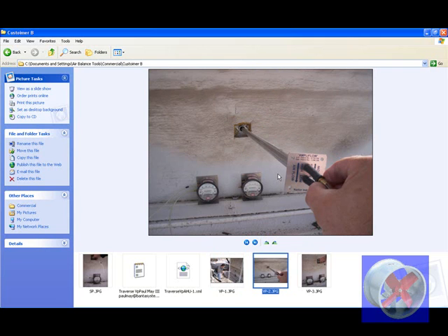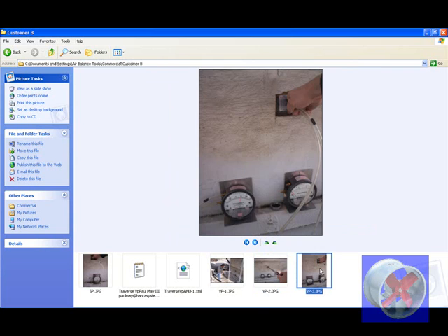So air is coming across this way. There's holes along this tube on both ends. These tubes lead into the magnehelic. We have the magnehelic high side and the magnehelic low side. The difference between these two is going to be the velocity flow across this duct in inches of water. So this will measure in inches of water, this magnehelic, and it's a gauge that goes from 0 to 0.25. Now we can see the pickup tube all the way inside the duct, and we can see our reading.